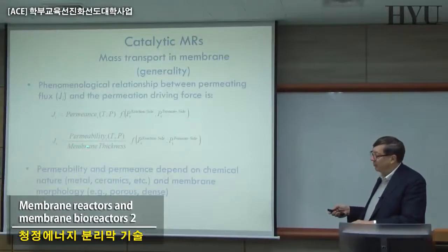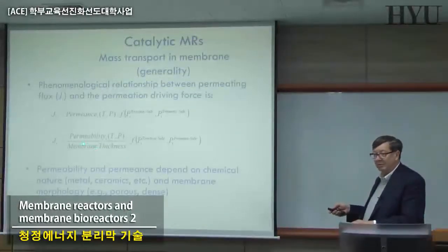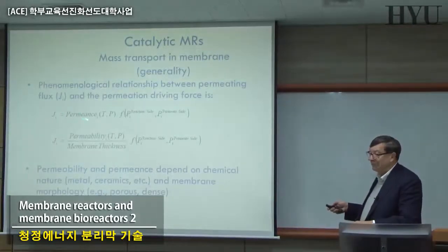And the difference is membrane thickness. So in general, when you don't know the membrane thickness, you have a permeance. And if you know the membrane thickness, you have the permeability. But in this case, there are different dimensions between the two parameters. So be always careful, they are not the same. The kind of relationship is the same.